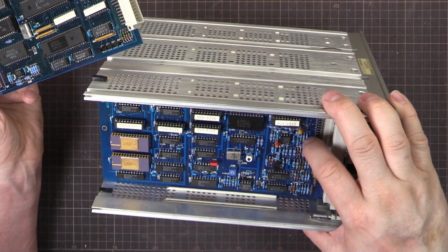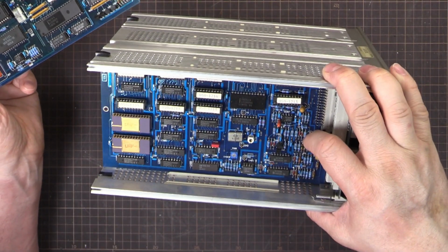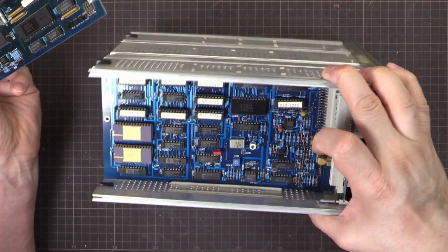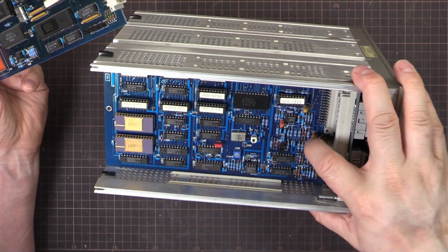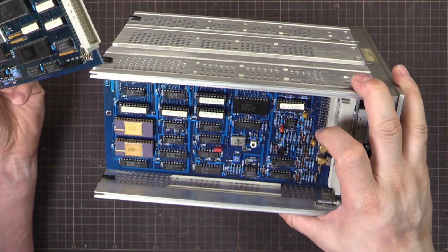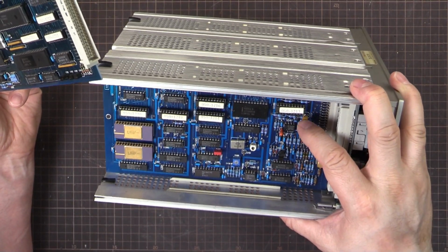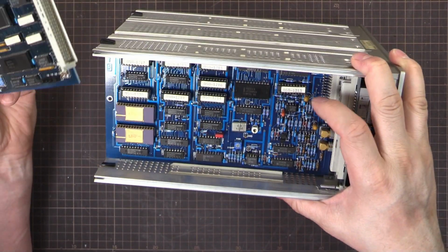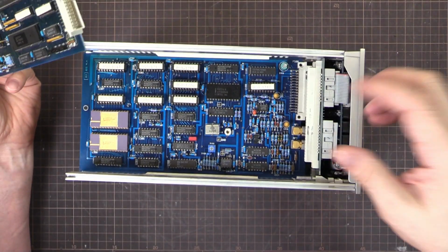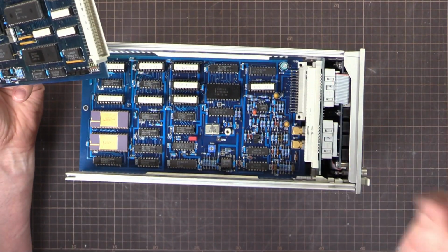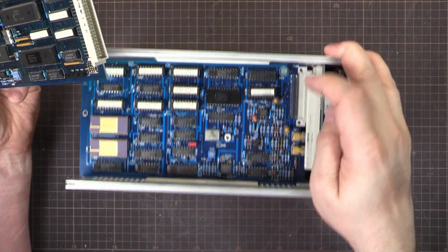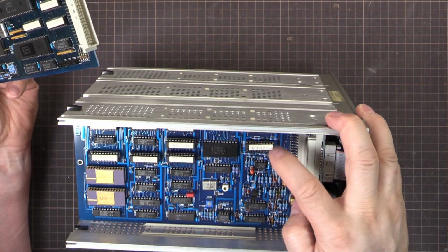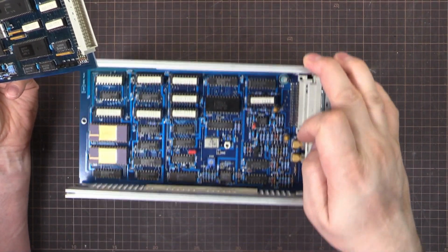They tend to go short when they get old. It's a known thing with older Tektronix equipment, especially much older stuff than this, talking 70s, maybe even 80s. You've got to watch out. I've had a few of them go short. I've actually had something working, then did some unrelated repairs, like cleaning the BNCs and all that sort of gear. Then I turned it back on and it wouldn't work, and it turned out in that time one of the tants went bad, so I just replaced that and it was good. So yeah, we'll be able to easily check that out.